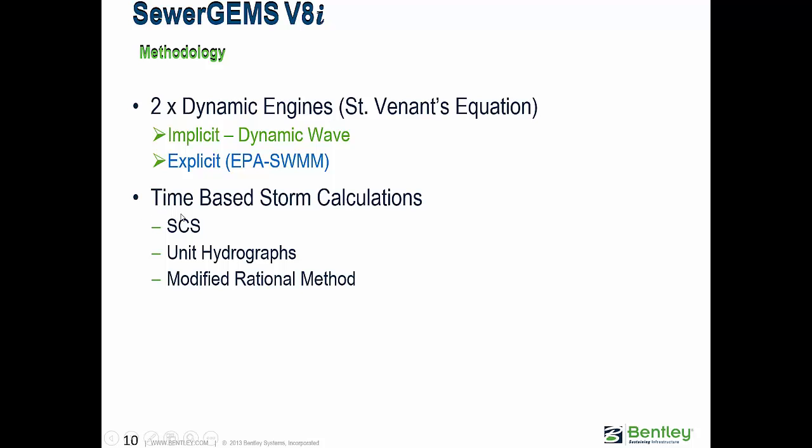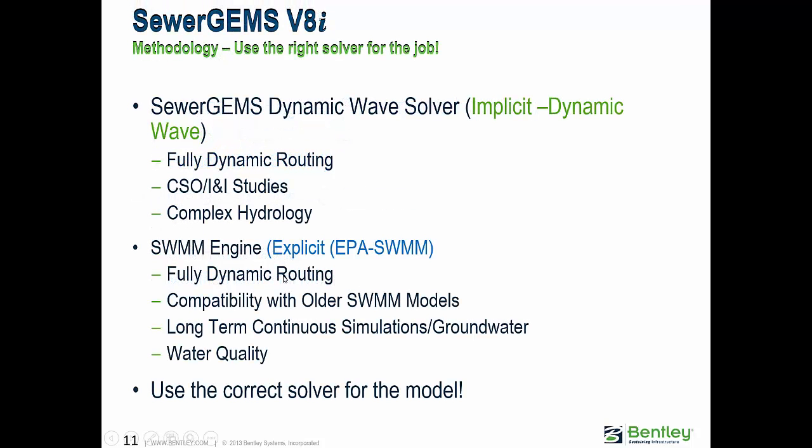Now these engines are used for calculations of storms based on time, which follows SCS methods. You can utilize unit hydrographs or even the modified rational method using these engines. The SewerGEMS dynamic wave solver does fully dynamic routing.